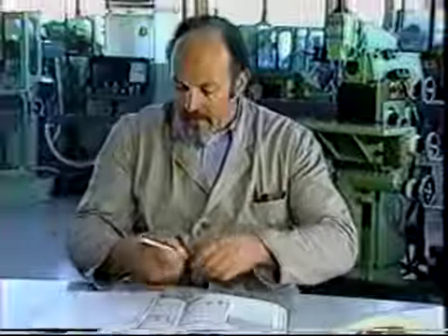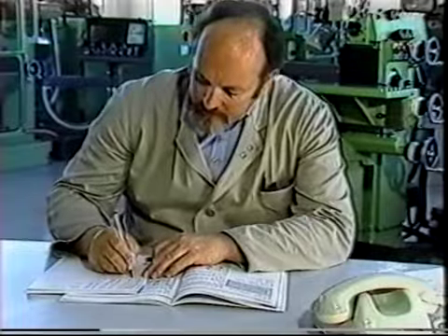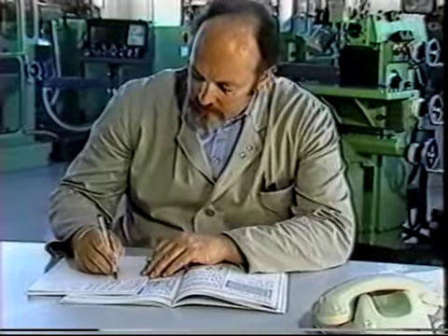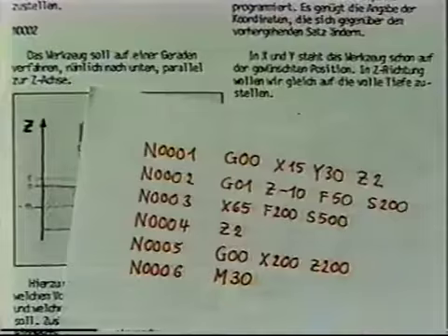Hey, hang on, not yet. The control system still doesn't know that was the end of the program. You tell it that with command M30. Well, so much for block number 6, M30. That's it for now. Now we're really through. We've just finished writing our first complete program.